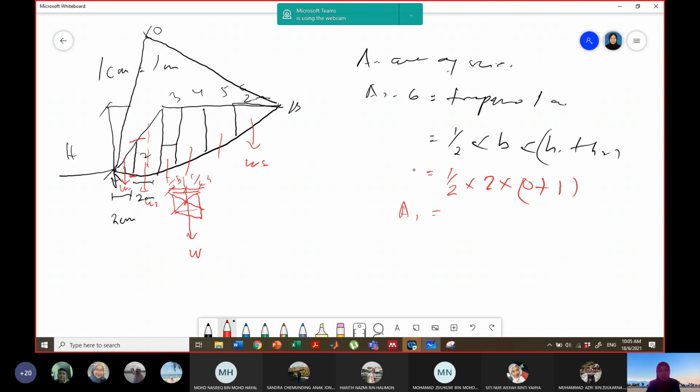Okay, if you remember, there are a few input parameters that need to be found. First is B, H1, H2, and then we have the area, the W, the alpha, the disturbance force, and the restoring or resistant force. The N is equal to W cos alpha, and the T is W sin alpha. Okay, B I have explained, the same goes for H and A, and W is the unit weight times the area.